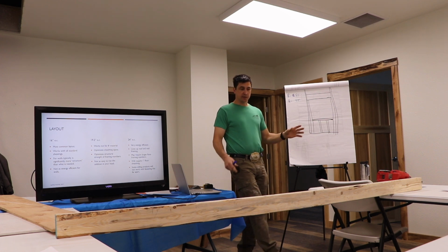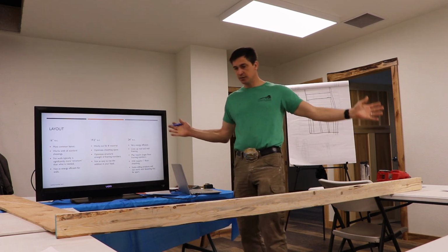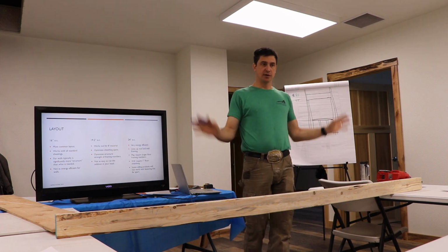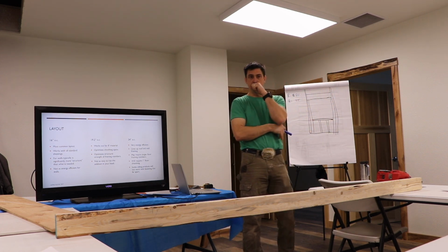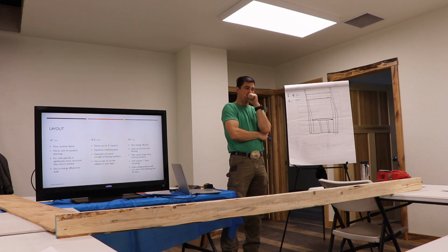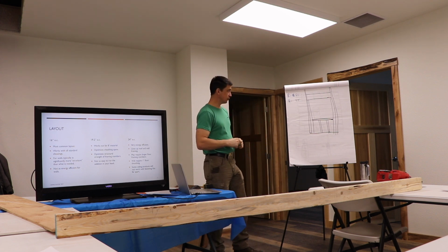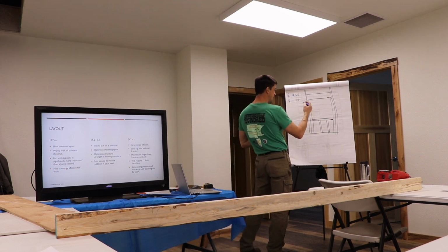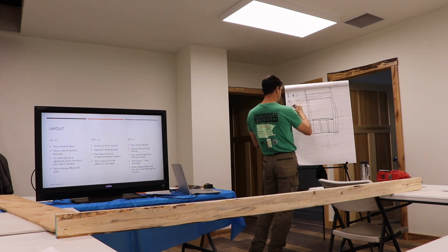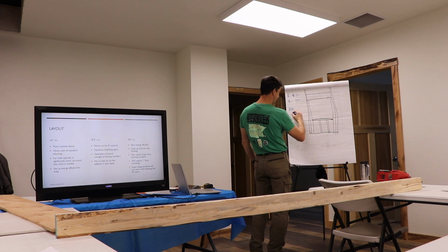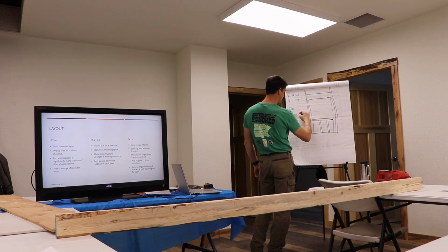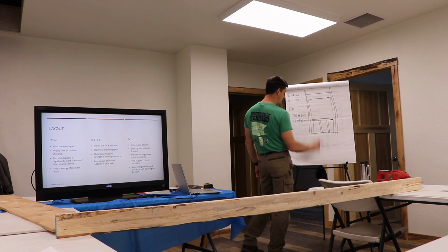So, if I take all of the framing in a typical home and lump it all together into one mass, it's generally right around a quarter of the wall area. So if I've got 1,000 square feet of wall, then I'd have 750 at R21 and 250 at R3.5.